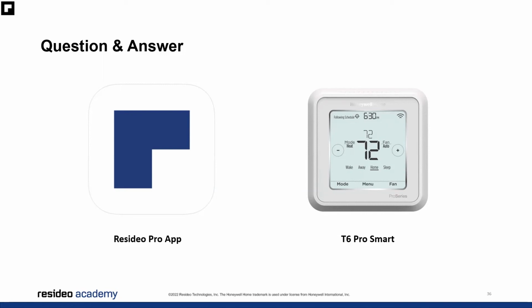Thanks, Isaac. Yes, so it really depends on what you're looking for. In general, anything from the 6000, 8000 series, so the Focus Pro, Vision Pros, the T9, T10, T6 can read an indoor sensor and either prioritize the sensor or average it. That has to be done from the setup in the ISU, as opposed to something like the T9 or T10, which is easier to do from just the interface within the app. So T6 is a good one for using indoor sensor averaging.